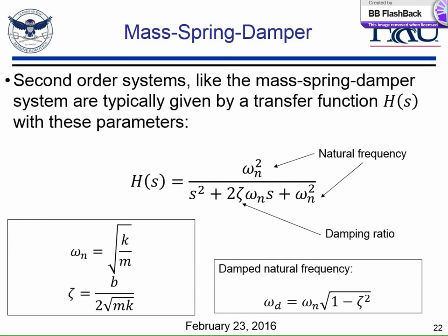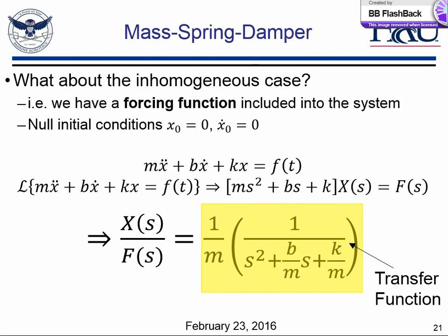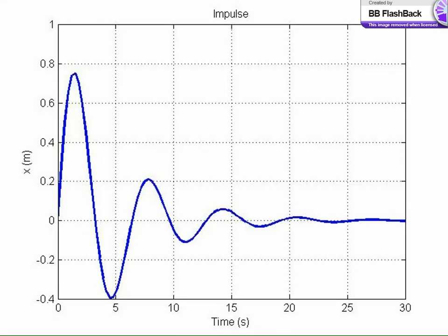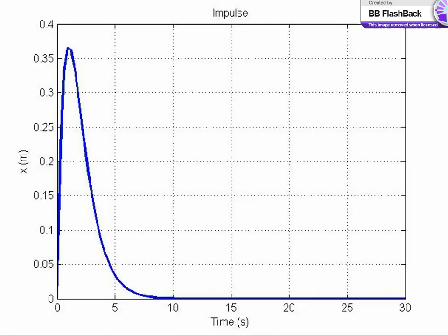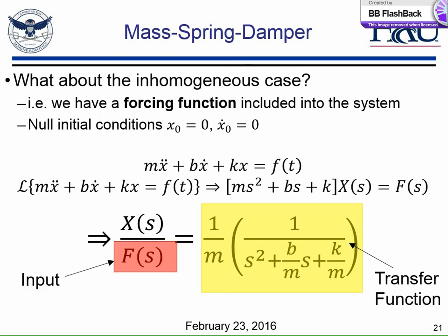And if we go back even further, we see that when we solve down the quadratic term here, that's essentially what we were doing. We were solving for the poles of the equation. And those three conditions that I gave you are represented all in those poles. You can just plot the poles like that, and then add a Laplace transform. So you have to have the Laplace transform to actually get your system into a transfer function. Right? Okay. So you don't need to do the inverse Laplace transform to solve it out. Okay. Right? So, I mean, you should do the inverse Laplace transform to solve it out because the poles really give you the best representation for it.